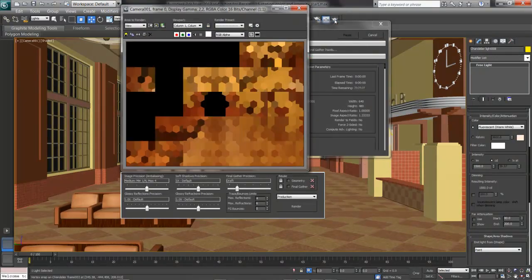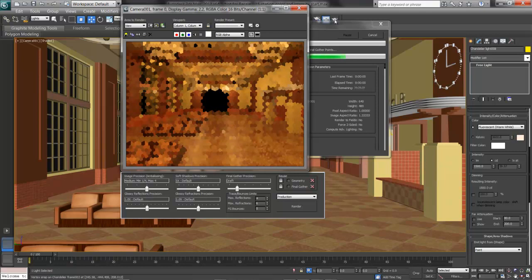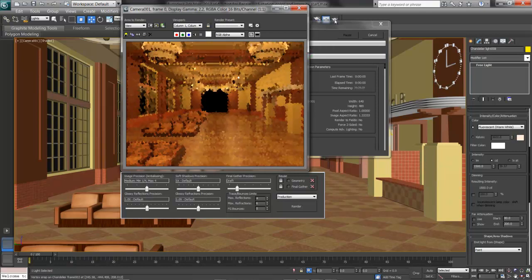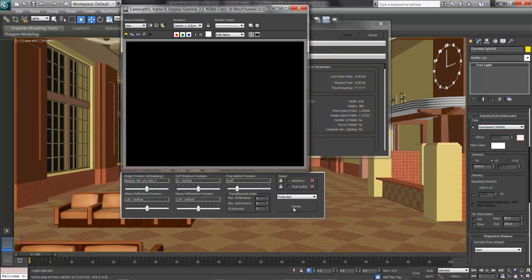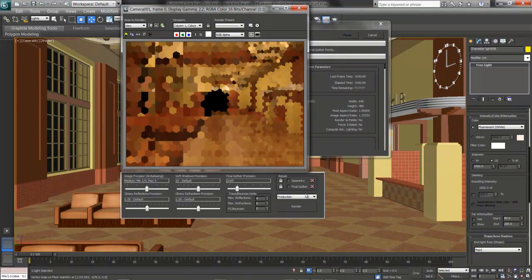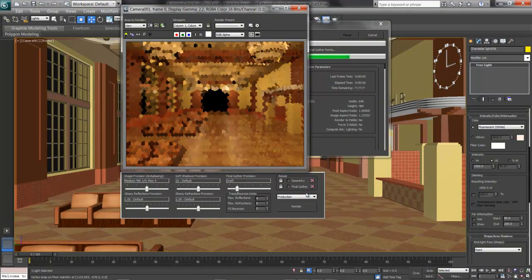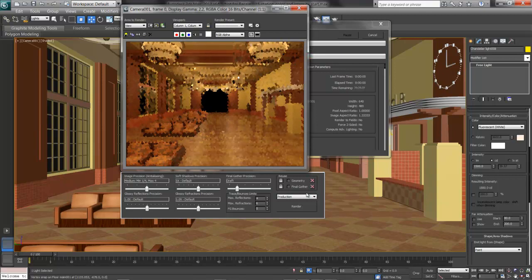Remember that because this adjusted all those lights in the chandeliers, they all changed, and my scene is a little on the yellow side. Something tells me the warm white is not the right way to go, so I'll try something else. Let's try instead a white fluorescent and hit render again. One of the big things with lighting is to test, and then retest, and test it again, but test it at a small size. It's looking better.